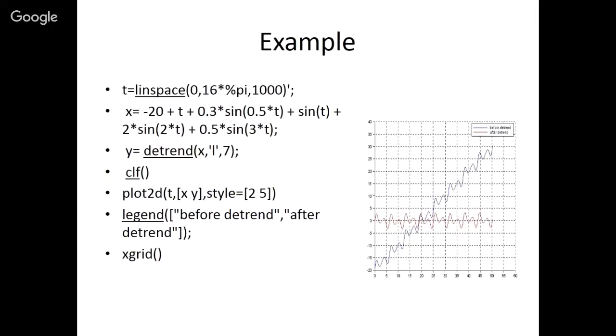For example, here we are giving 7, meaning after 7 pieces, 1, 2, 3, 4, 5, 6, 7, you get the breakpoint. That means it will cut at number 7, the constant and also the linear signal. That is your breakpoint. If you give the breakpoint as 9, nothing will happen. Otherwise, nowhere are we saying it will start from 0 or something, right?